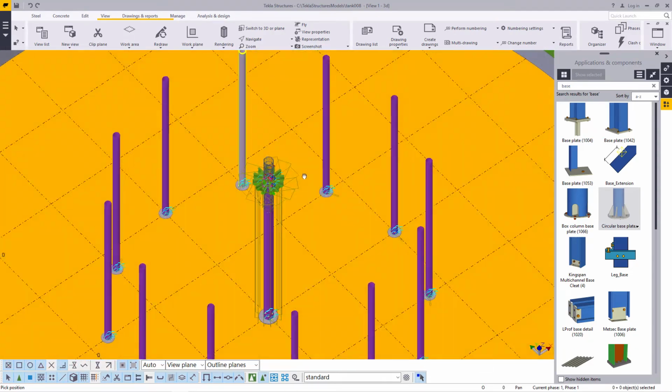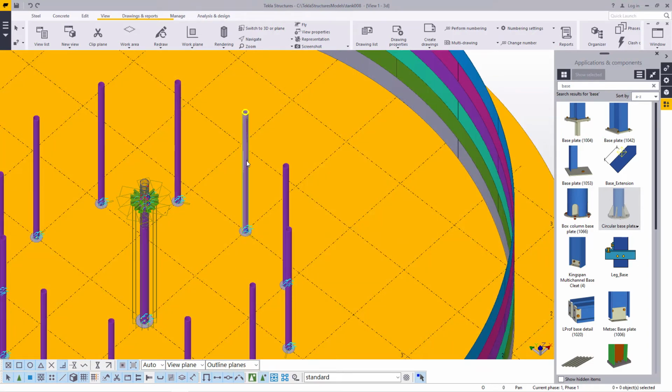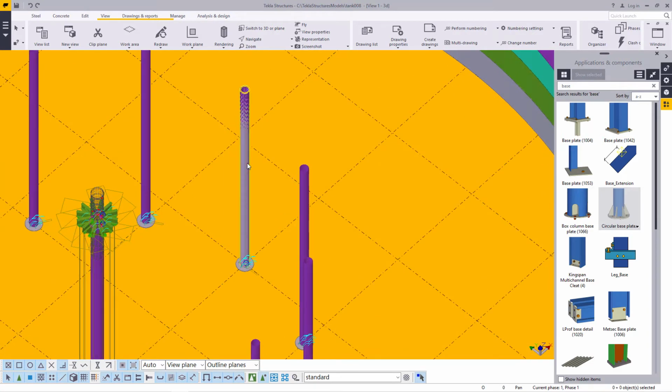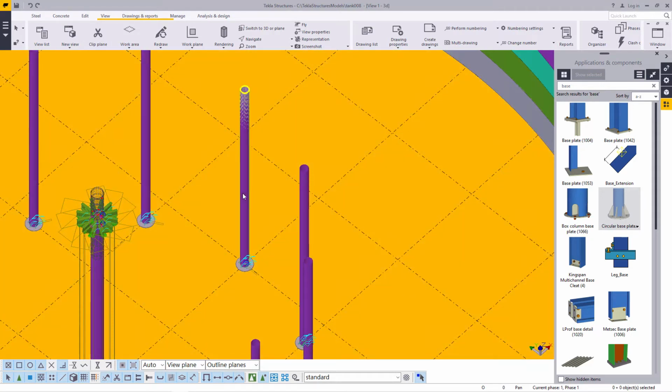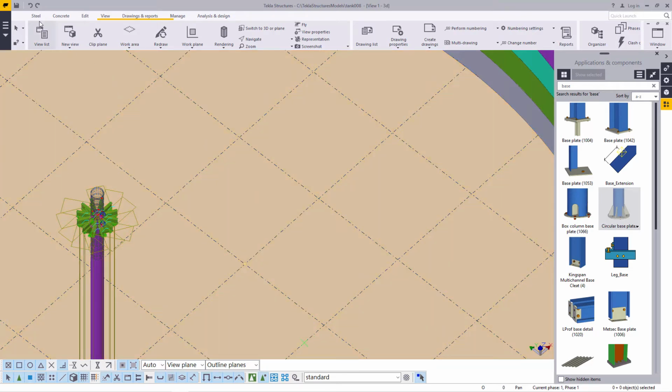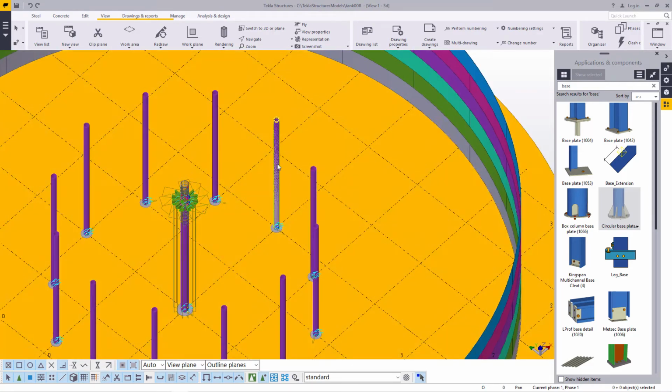So in this particular case, once again, I'll come all the way here. You can see we have a member duplicated right there. So you remember, if I delete this, I'll lose all the members. So this is the master. It is the mother column that connects all this. So if you delete, you lose everything.